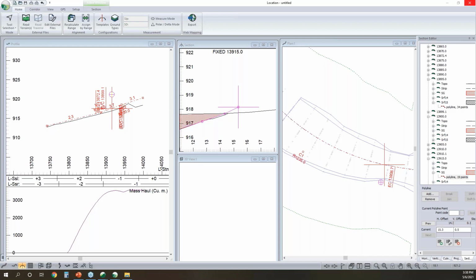Next one, can you show an example of a method of tying off final surveyed surface to original ground in cross section, like how you extend an individual line? So yeah, we'll circle back on that. It's similar to the previous question. We'll reach out to you guys, and yeah, so there's a way to do it in here, and for some reason I'm drawing a blank, or it's not behaving for me, and then there's another way to do it in the terrain module where we can set the terrain grade out from our surfaces to another surface. So both are useful, both have their place.